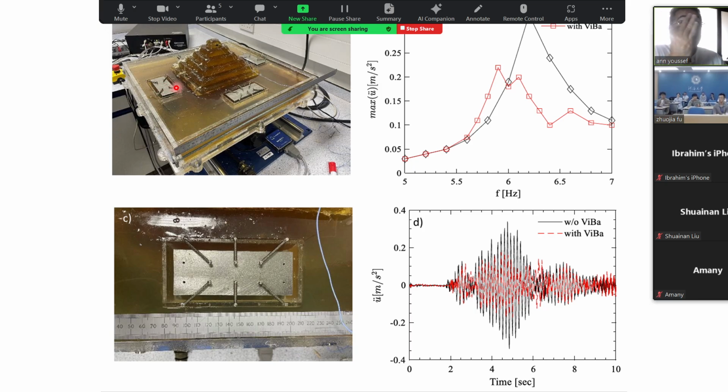So these are the three factors we always look at. For example, if we move this barrier a bit away from the pyramid, we will have a different type of reduction. So we are searching for the optimum place to install these vibrating barriers, and we search for the spring stiffness and the mass of the vibrating barrier we are going to install.